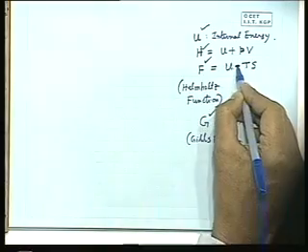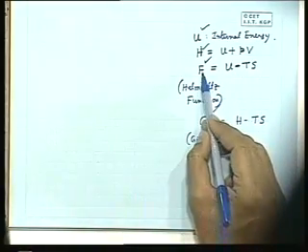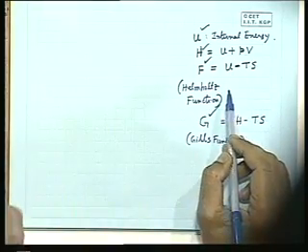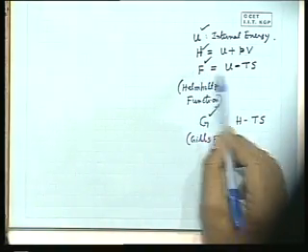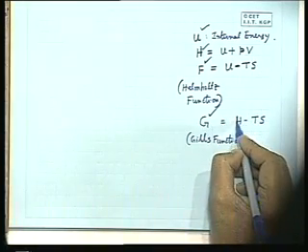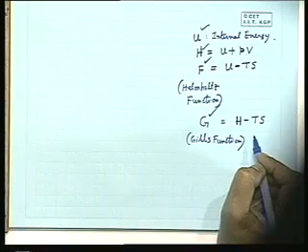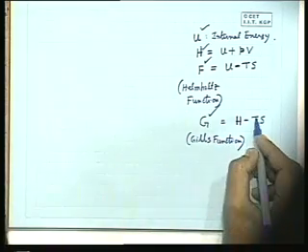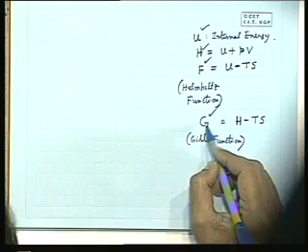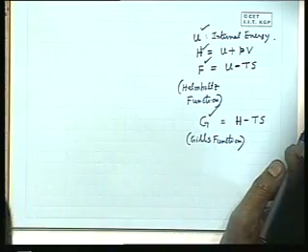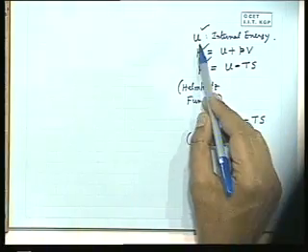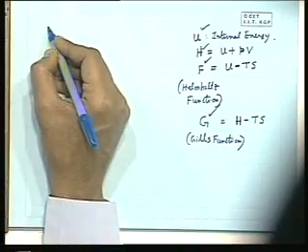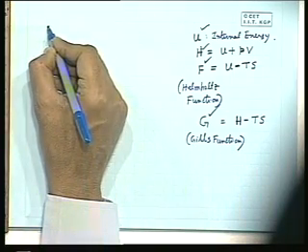So this I told you as far as the physical significance of the Helmholtz function and Gibbs function is concerned. But at the present moment, it will be sufficient to know how these Helmholtz and Gibbs functions are defined. Afterwards, when we start the thermodynamics of reactive systems in this course, we will be able to find out the physical significance of the Gibbs function in more detail. So at the present moment, if we just recognize the definition of these four functions this way, now I can write the differential expressions of these.